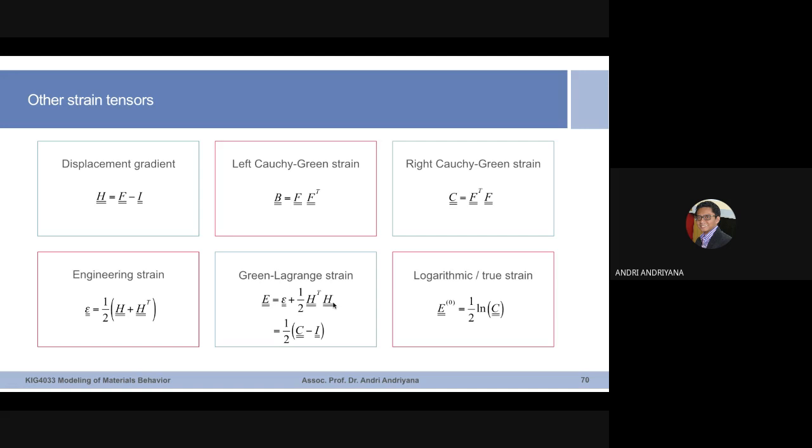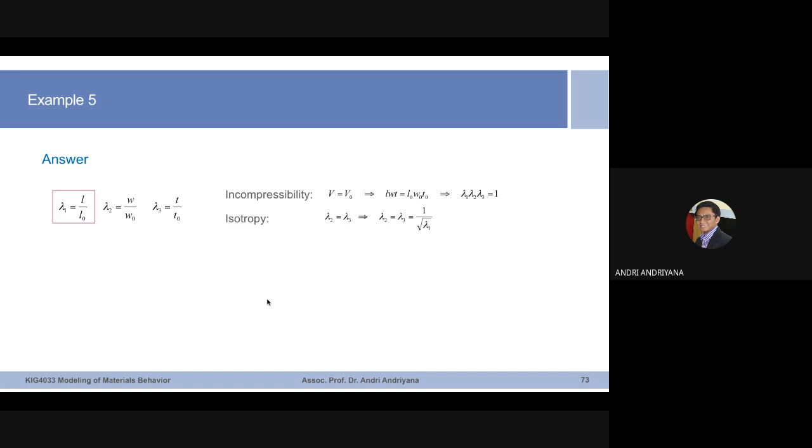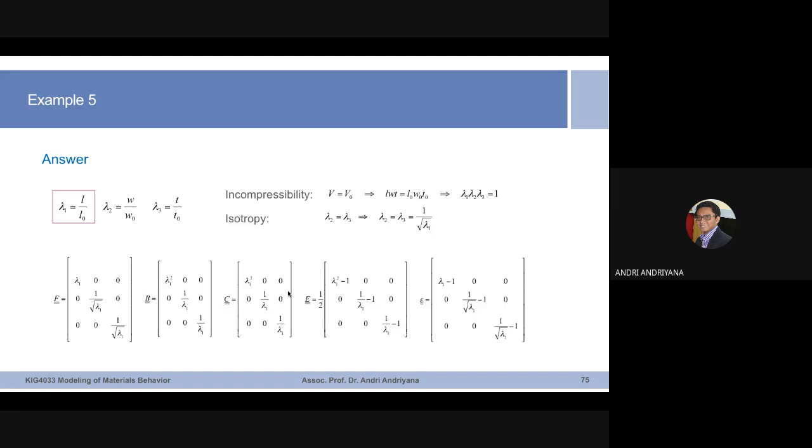deformations. So true engineering strain is a good measurement, but it is a very simple one. In the case of large strain involving non-linear deformations, then Green-Lagrange may be more suitable to describe the strain. It is also the strain. And in the case of uniaxial extensions, it is half of lambda 1 squared minus 1. That is from the equations. In the same way that engineering strain is simply lambda 1 minus 1. So C, from a mathematical standpoint, is also lambda 1, but squared.